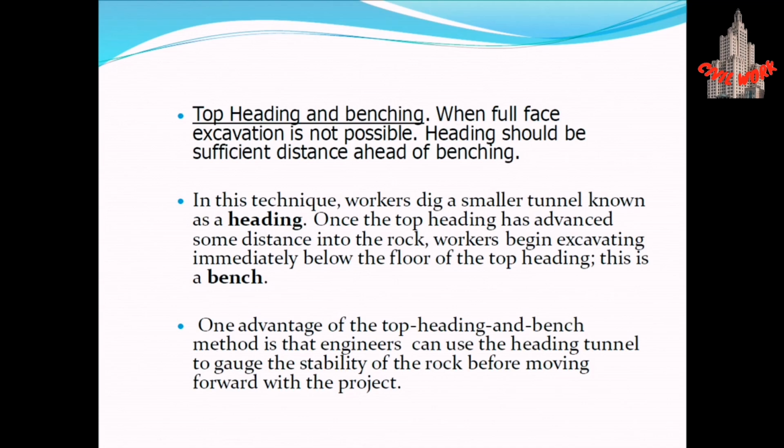In this technique, a worker digs a smaller tunnel known as a heading. Once the top heading has advanced some distance into the rock, workers begin excavating immediately below the floor of the top heading. This is a bench. One advantage of the top heading and bench method is that engineers can use the heading tunnel to gauge the stability of rock before moving forward with the project.